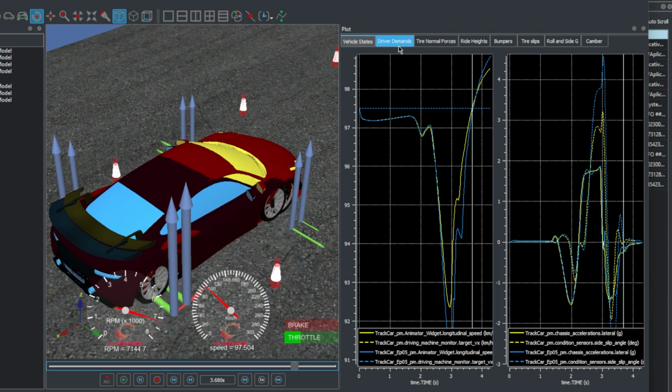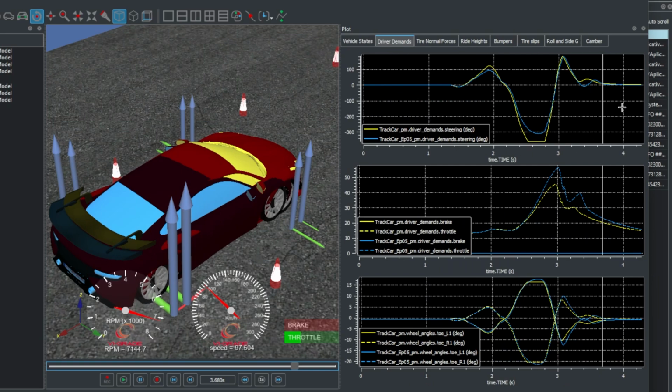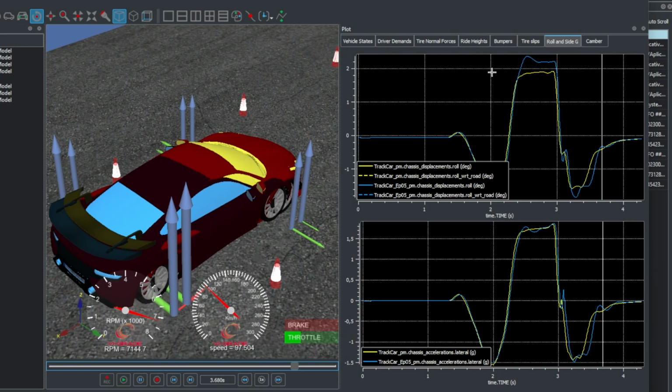If we observe the steering profile, the first plot under the Driver Demands tab, we will notice the new car requires more steering around the apexes of this maneuver. We can also observe a smoother, more dampened steering profile as the car straightens out of the last transition, with no overshoot. Both of these are indications that our changes to the roll centers and toe variation led to a more stable car. If we plot the body roll data, we can see a decrease around the maximum values, as desired, meaning we do, in fact, need less loads at the springs and anti-roll bars to control that parameter.